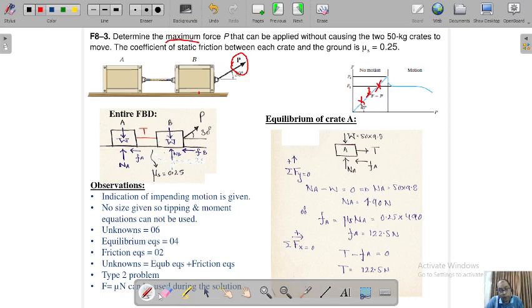So if this force is maximum, then from this graph, the maximum position of this graph is only one, and at this position the static friction will be maximum, and where it is maximum, this P will also be maximum, because F is equal to P. He says F is equal to P. So if you look at it, can we solve this problem directly?